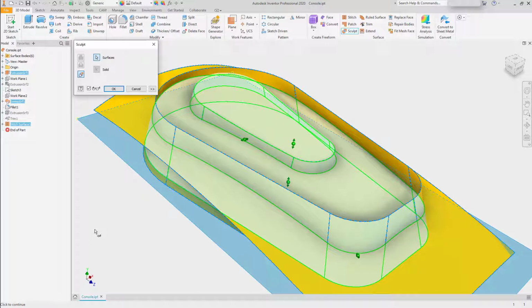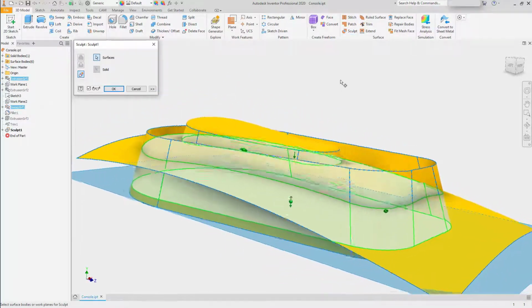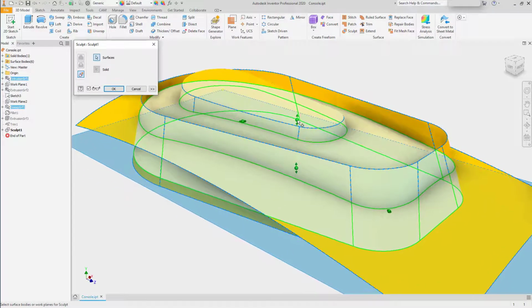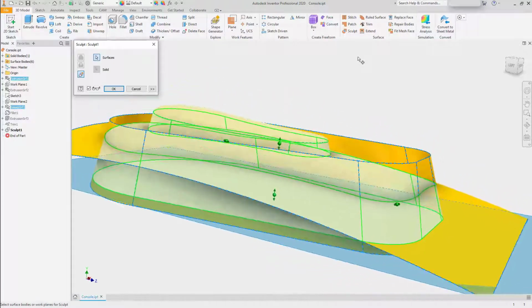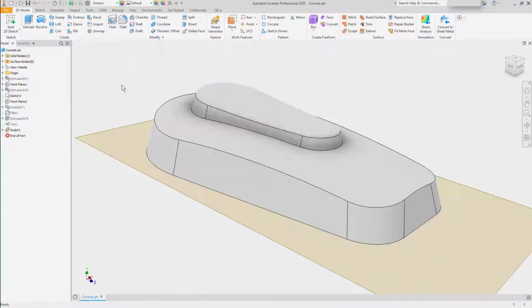The arrows that appear will allow you to toggle which side geometry would be created on or removed from. In this model, there are no voids, so we won't be able to pick and create a pocket. But to test it, if you click the bottom arrow, it will generate only the lower portion of the model. Or if you click the ball in the middle, it will include everything. When you click OK, it will generate the solid model.